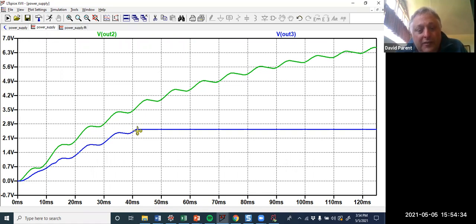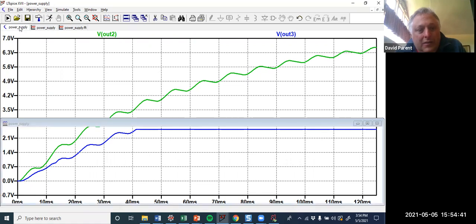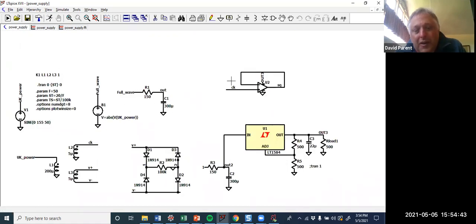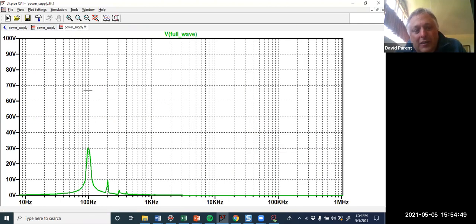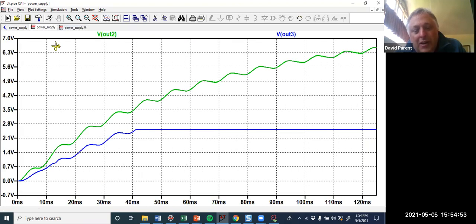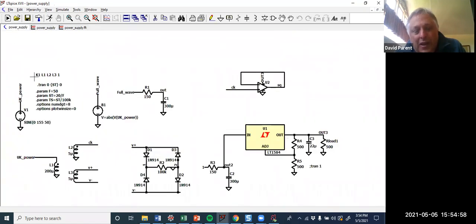All right, this isn't 5 tau. That's just the output reaching what it needs. You could calculate what 5 tau was, right? But the smaller the cutoff frequency to get rid of more high frequency harmonics, the longer it's going to take for your power supply to react.